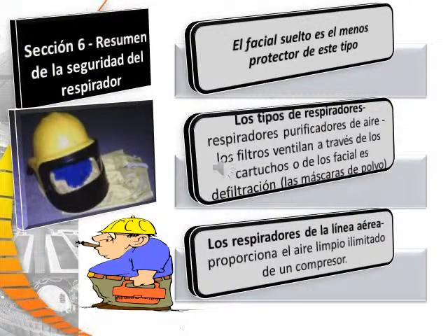Loose-fitting facepieces are the least protective type. Types of respirators include air purifying respirators, which filter through cartridges, and filtering facepieces. Airline respirators provide unlimited clean air from a compressor.